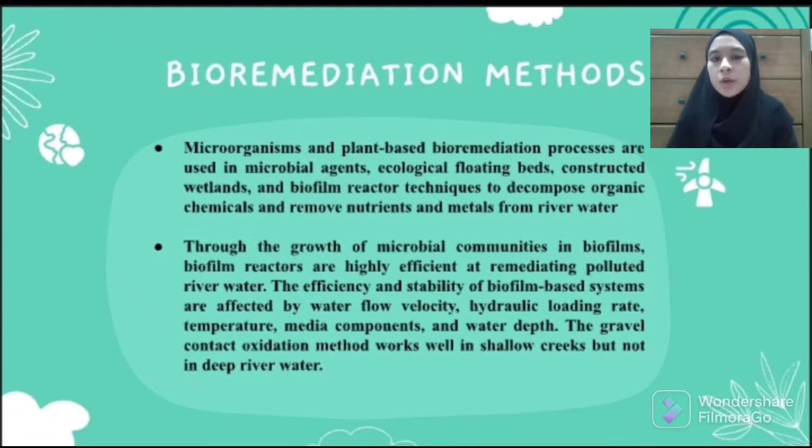Through the growth of microbial communities in biofilm, biofilm reactors are highly efficient at remediating polluted river water. The efficiency and stability of biofilm-based systems are affected by water flow velocity, hydraulic loading rate, temperature, media components, and water depth.